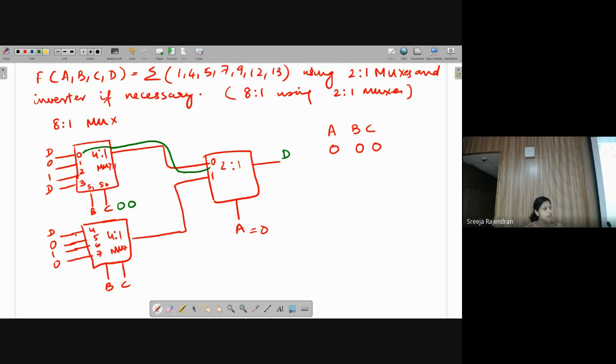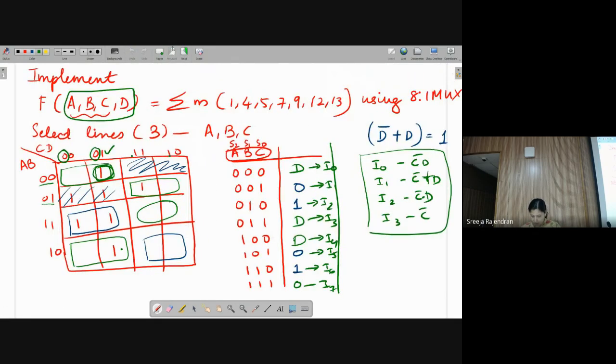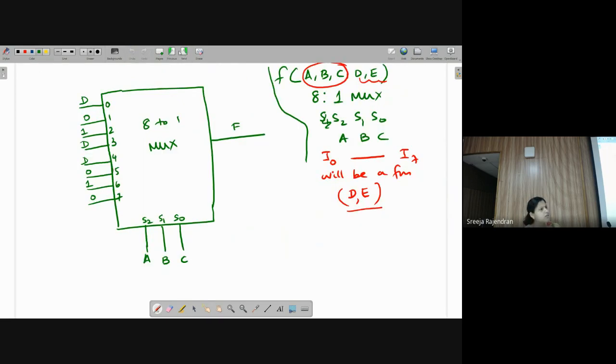So in fact, it comes in the same order as you have generated for a large multiplexer. That's why I wrote, even if you split it, the first 4 will go in the first multiplexer, the next 4 inputs will go into the next multiplexer if you have computed it separately. Just from this truth table that we have written here, in the same order, you can put it onto the muxes, whichever smaller mux you have. Now, is that okay? Ketan, what is your question?